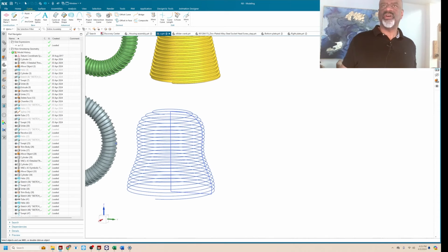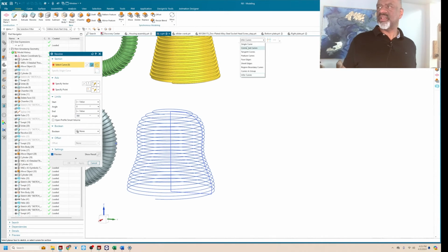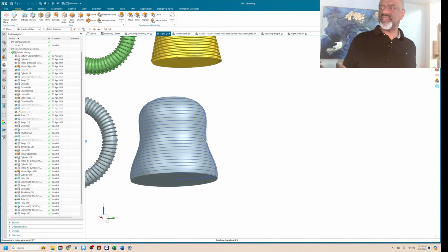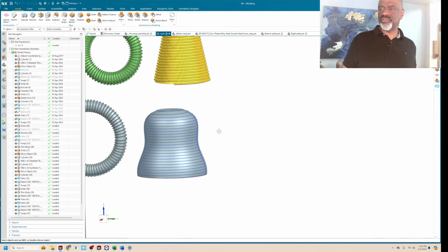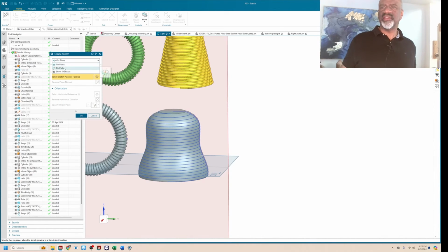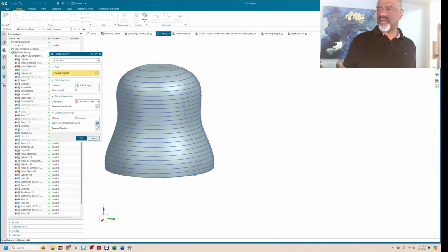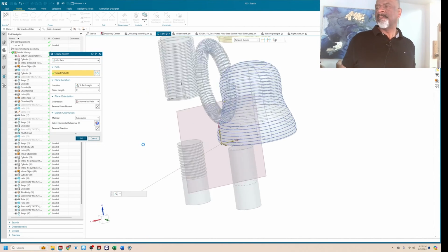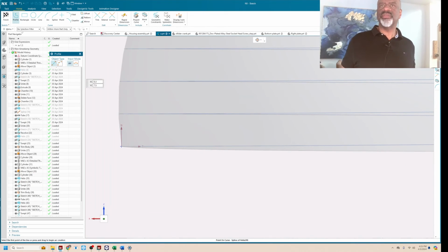Awesome. So what I'll do next is go to the revolve function, revolve, and I'll select just that crazy spline, and I'll revolve it about the center line like so. As you can see, the helical form is distributed on the revolved surface. And I will finish off with a sketch on a path. I'll grab that path. I'll call it 0, where it's starting. I'll say OK. And then I will create yet another tooth profile.